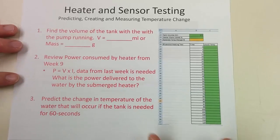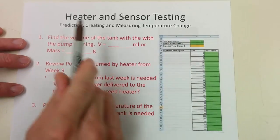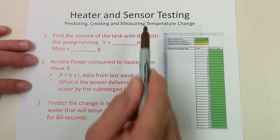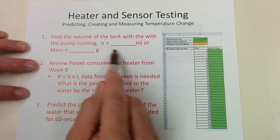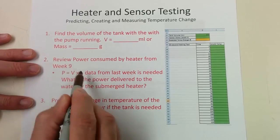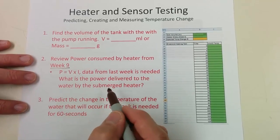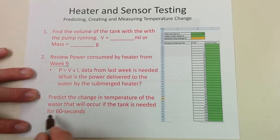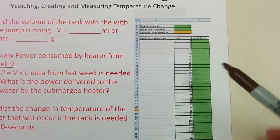The final activity you'll do in class is to check the heater and sensor testing. All right, we want to predict, create a temperature change, and then measure that temperature change. All right, so we'll get to the formula here a little bit, but one thing you're going to need is the volume of the tank or the mass of the water. Right? Also, from week 9, you're going to need the power data from your heater. How much power is your heater delivering to the water when it's submerged? And then finally, we're going to predict that temperature change. This is the graph that's shown on the data sheet in the online materials, and you'll be completing it.